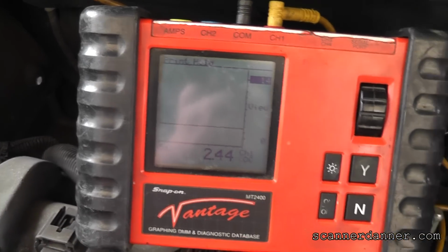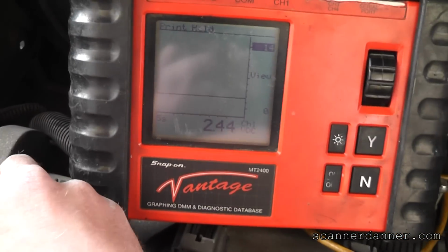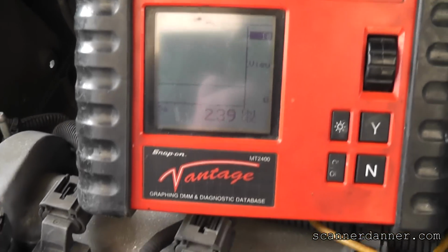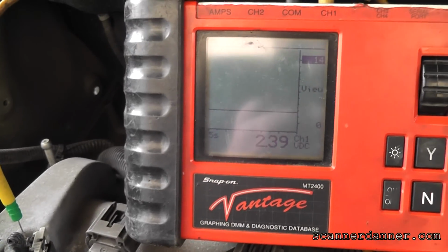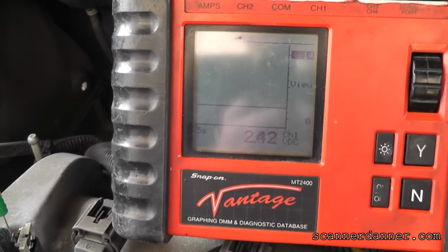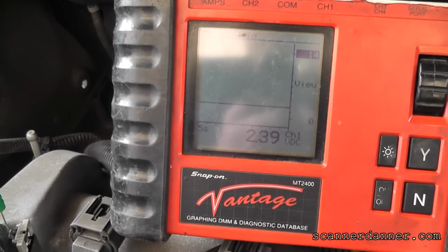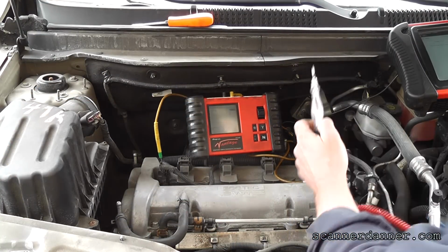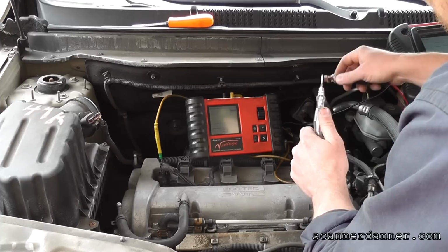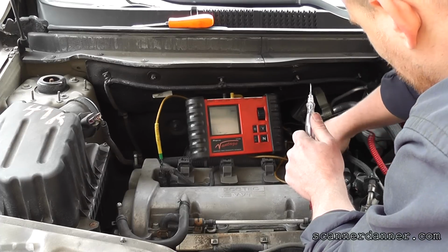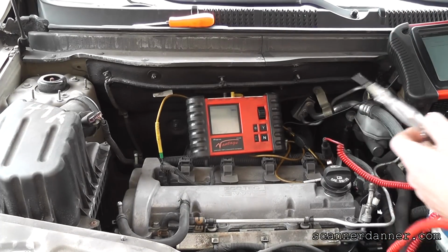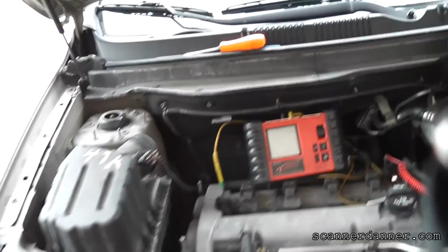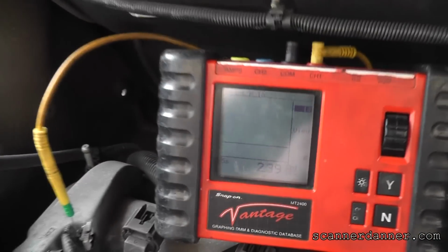Almost raising, I don't know if we want to call this one a bias or not, raising the voltage. I know the controls are good. You know what I can do is I can simulate a good solenoid with a test light. Hold on one second, let me do that. So what I'm doing with this test, I know this solenoid's open, guys. I'm going to go test light to ground, check my light, make sure it lights. Okay, good. And then I want to trick the computer into thinking this solenoid is good.